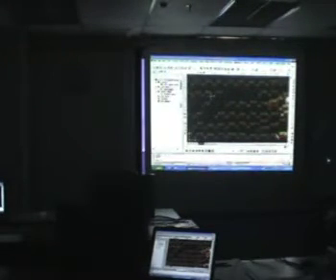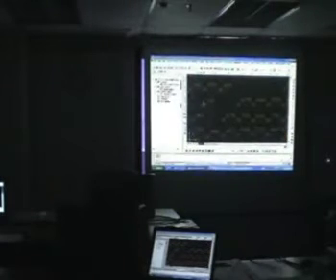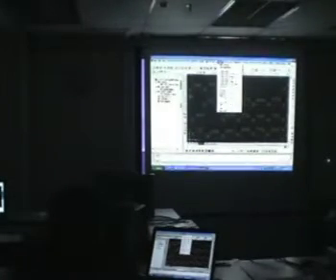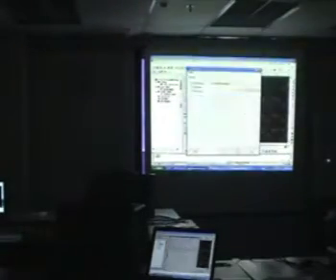A little bit more about this: this marker, this cross, indicates the position of the point. This blue marker here. The yellow text indicates the point number, the red indicates the elevation value, and the green color represents any description you want to attach to the points. Let's say, for example, the surveyor goes to the field and indicates that at this particular point there's a tree, or there's a drain or road line, wall. You can attach that kind of information in here as well. So at least you're not just looking at points and not knowing what each represents. Just to give you an example, I'm going to edit this point.